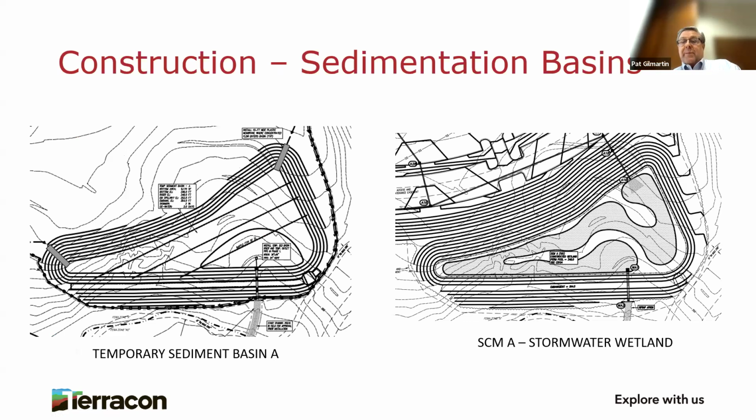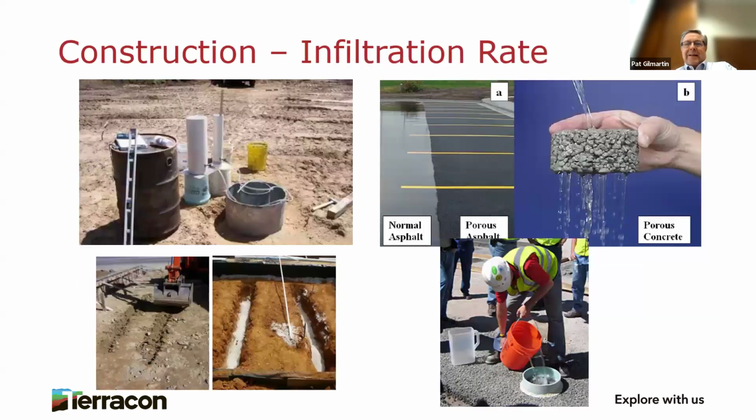The construction of temporary sedimentation basins should be observed and tested during the initial construction before they fill with water or sediment. It's really difficult to perform adequate compliance testing at the end of construction if the embankment and the outfall pipe were installed months before during the initial construction. I've had projects before where they've called us up and said, well, we built our pond, come certify it. I'm like, when did you build the pond? Well, 9 months ago when it was a sedimentation basin. We weren't out there testing and observing at that time. How can you expect us to certify its compliance with your plans and specifications?